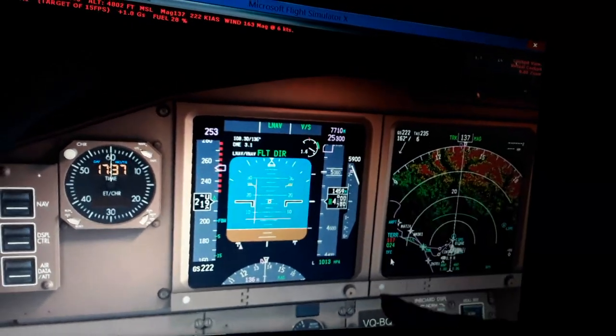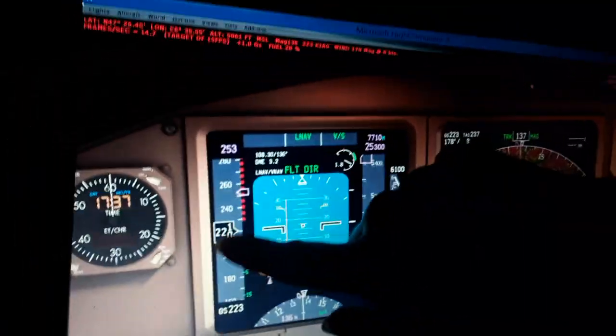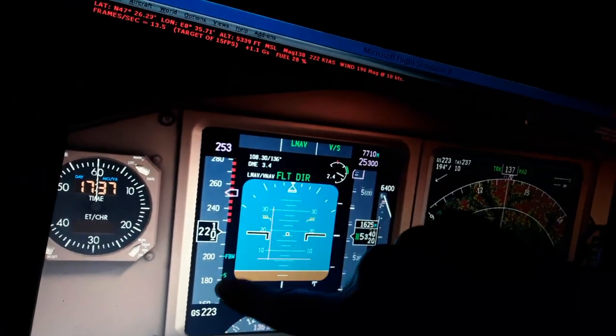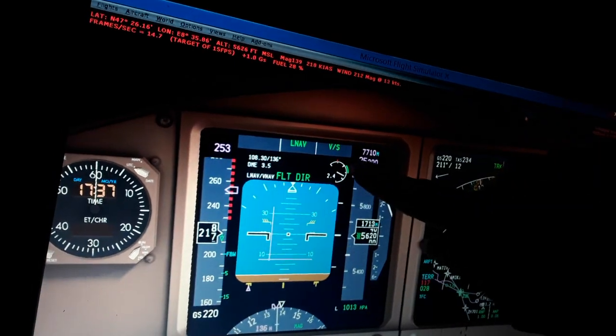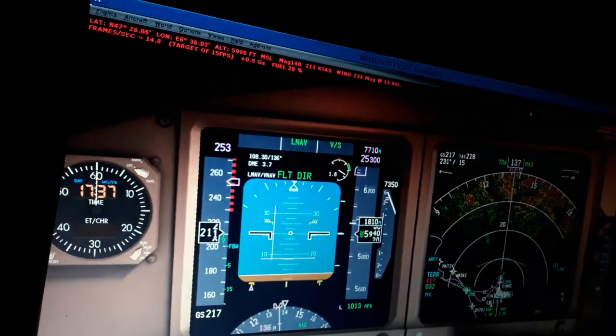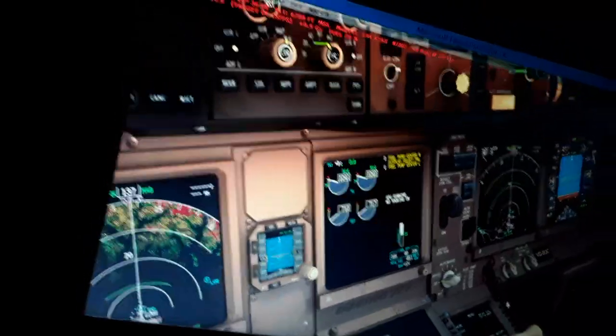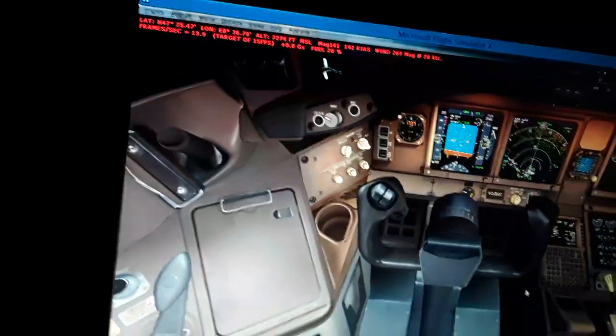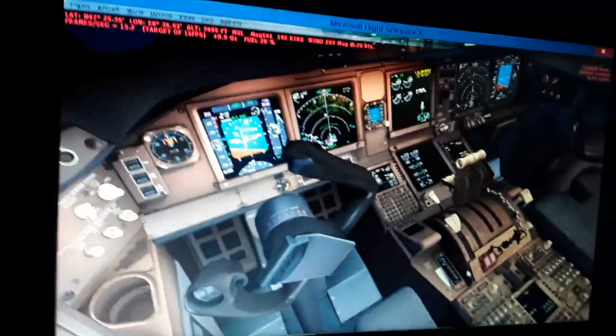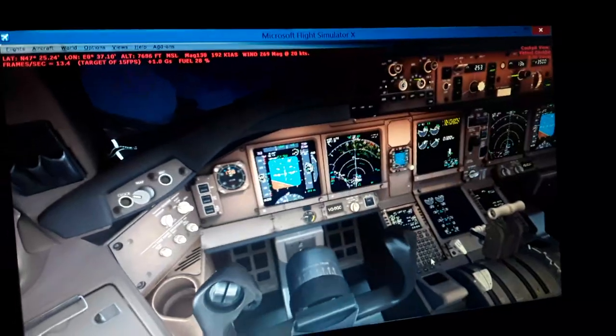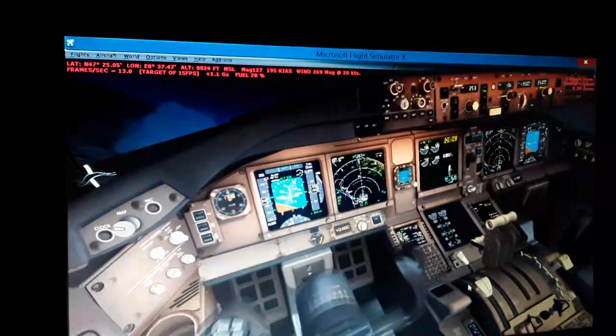We climb at 5,700 feet per minute. The airspeed is 220 knots. The flaps are also at the limit, and the target airspeed, target altitude, and the terrain, and now the map over here. We also have the engine set over here, maximum takeoff, and the autopilot set. So you can see we can start turning now. Make a turn. You can also have the outside view.